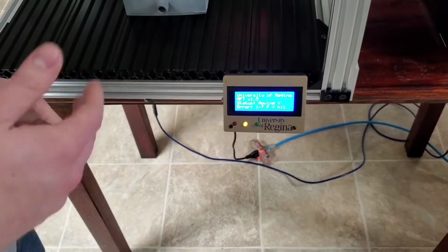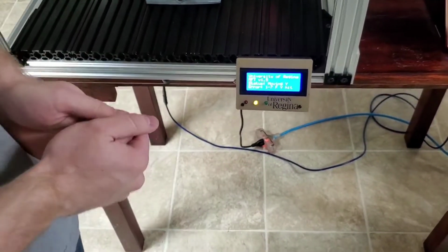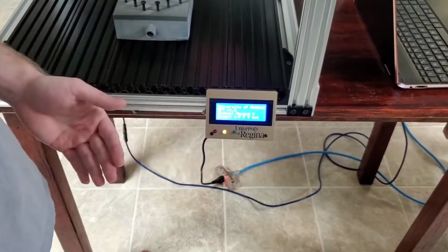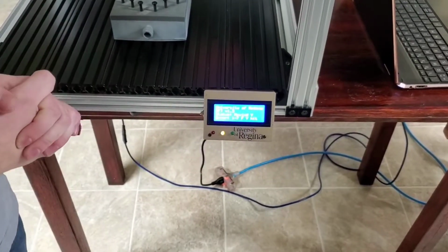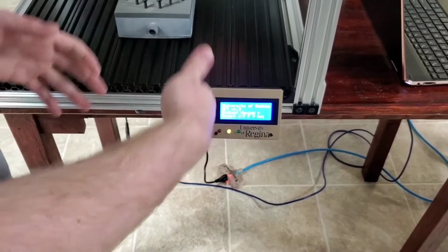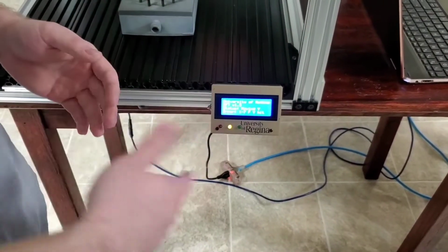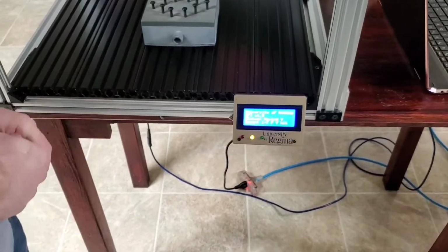In our case, we actually implemented the limit switches as fatal errors, but for future improvements, they're obviously going to be recoverable errors, but right now we consider them fatal. So we've maintained that same architecture. While it's technically fatal in its current stage, our future improvements would basically have it rehome again and then continue on working. And if it repeatedly hits a limit switch, then it would do a full reset. But that was not currently implemented at this point.